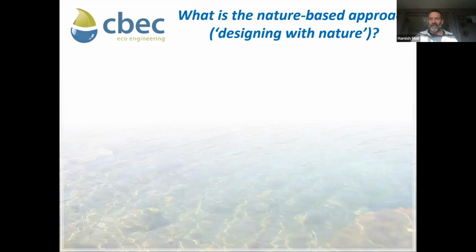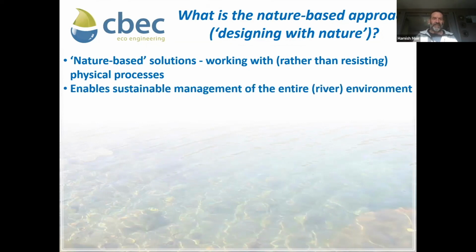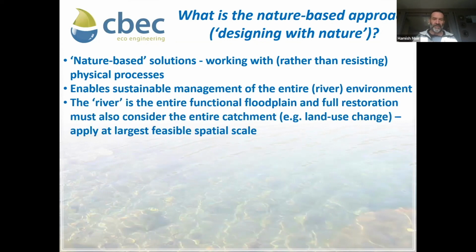What is the nature-based approach? Fundamentally, nature-based approach or nature-based solutions is working with rather than resisting physical processes in the river environment. This enables sustainable management of the entire river environment, and that's quite important in terms of the definition of the river. We don't think of the river just as the channel, the low flow channel. It includes the entire functional floodplain, and if one were to consider, in a holistic sense, the entire river catchment, the entire watershed. So we're looking at valley sides and headwaters and estuary areas as well.